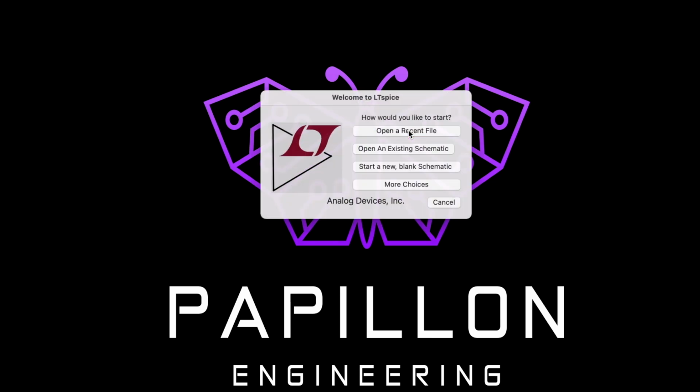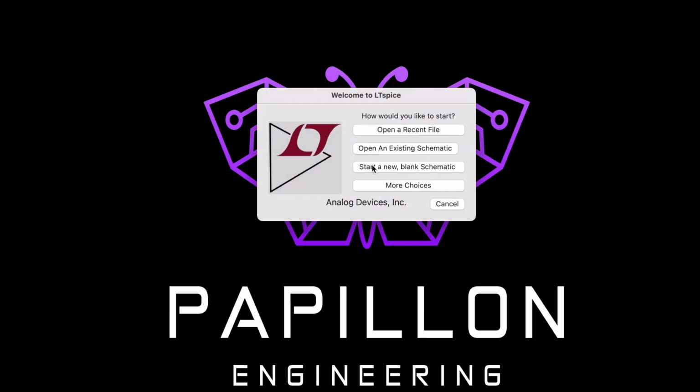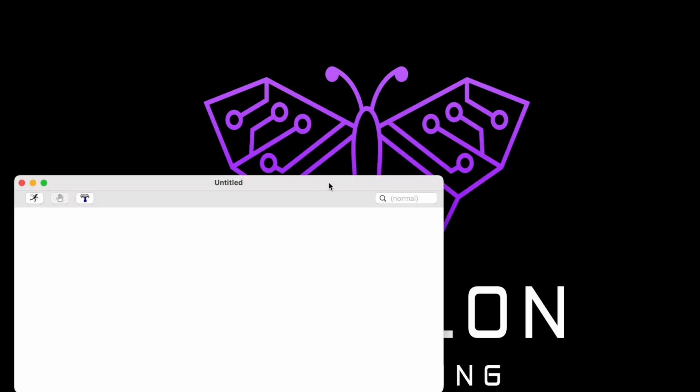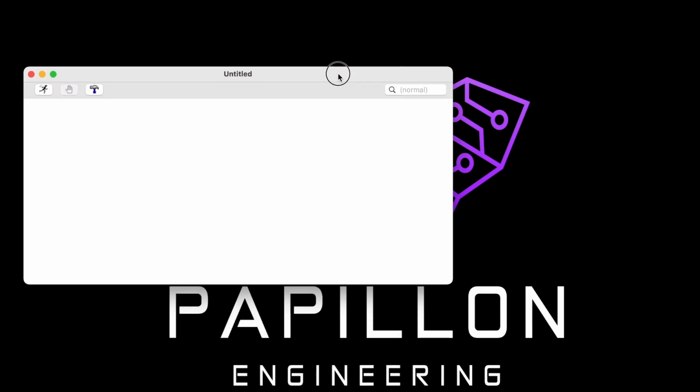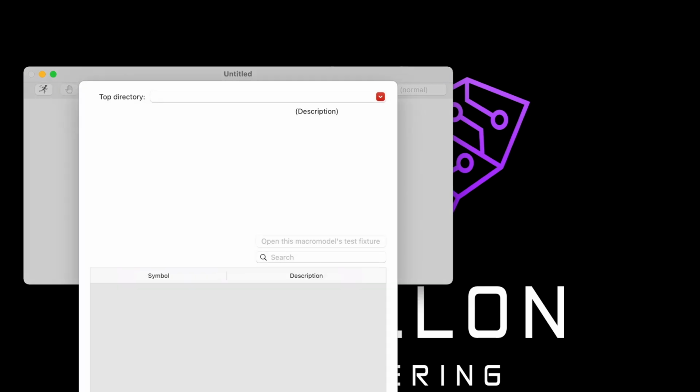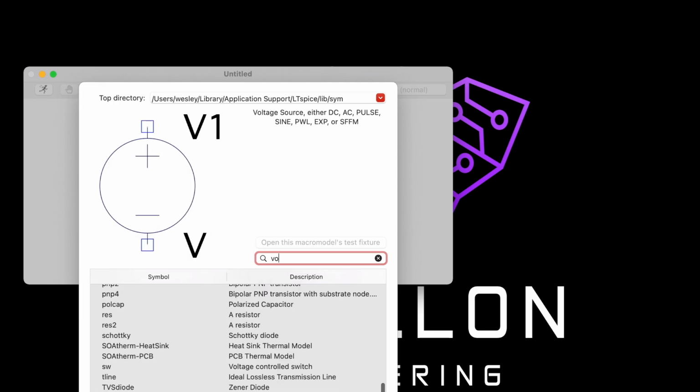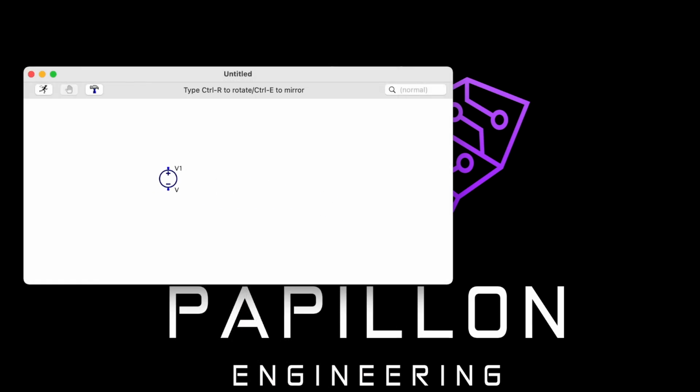Okay, so this time we're going to cover parallel circuits with LTspice, and continuing from what we learned from the series circuit in LTspice, we're going to look for our components. We're going to go to draft, or hit F2 for the component screen. I'll just use 2 components for now, voltage source and resistors. Later on, I'll cover capacitors and inductors as well, both in DC and AC.